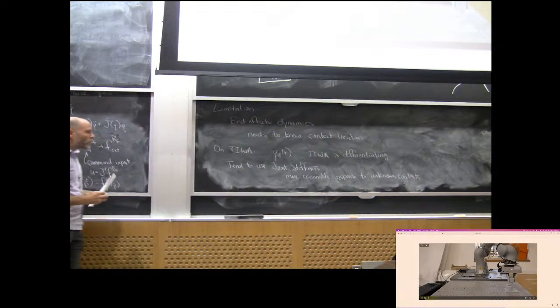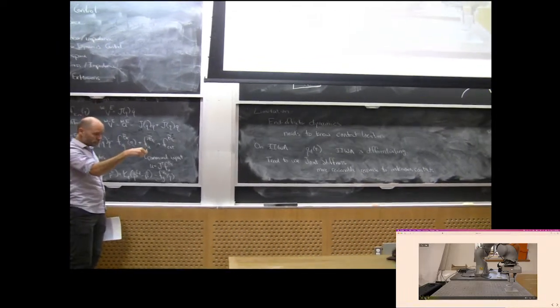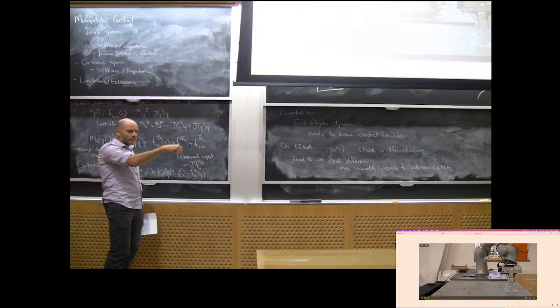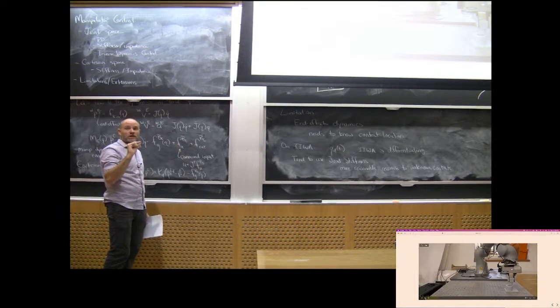And an important point that I maybe forgot to make: the difference between the stiffness control, which is canceling out gravity, versus just a PD control, is that if I can cancel out gravity with a feed-forward gravity term, then I can choose my stiffnesses to be much softer. I can choose KP and KD to be much smaller if they don't have to also fight gravity.